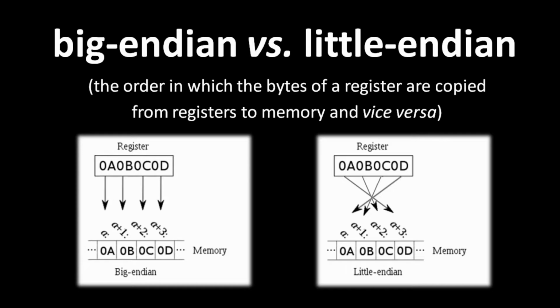Likewise, all Western convention tells us to write numbers with the most significant bytes on the left. So if we think of memory horizontally, it makes no sense whatsoever to use little endian. Unfortunately, for historical reasons relating to performance, Intel and some other CPU makers chose to use the little endian scheme. Those reasons no longer make sense with modern hardware, but the x86 architecture is still stuck with little endian byte ordering.